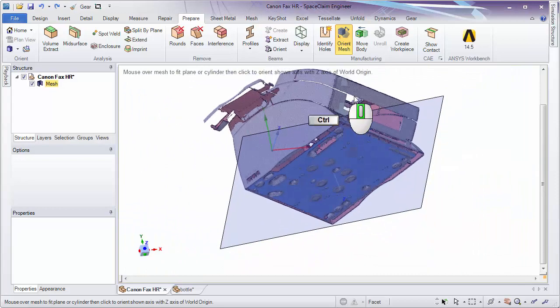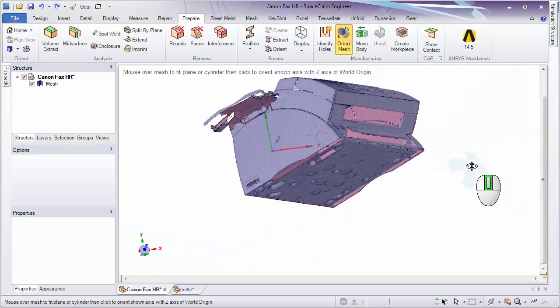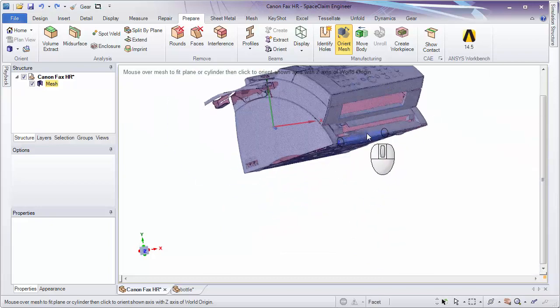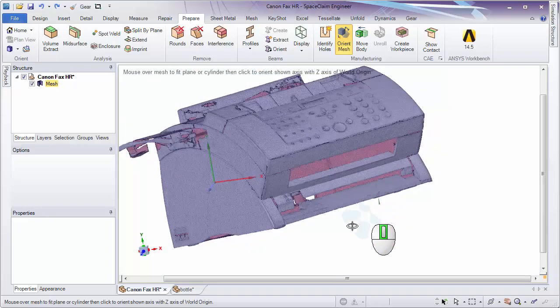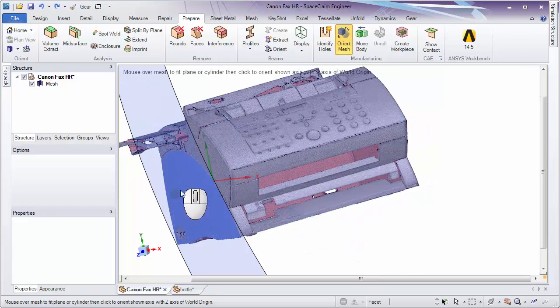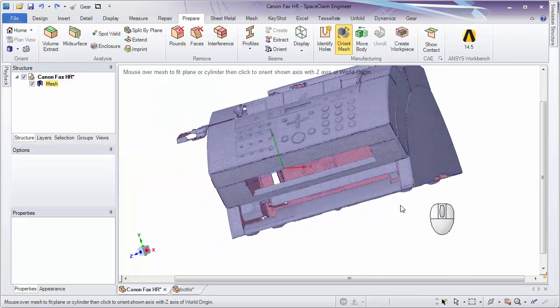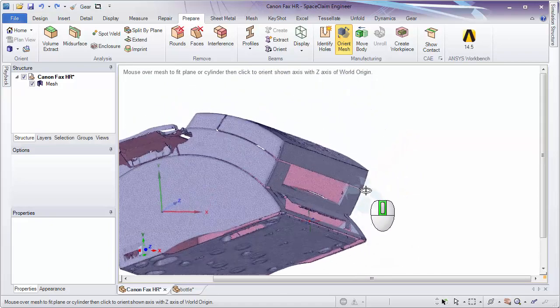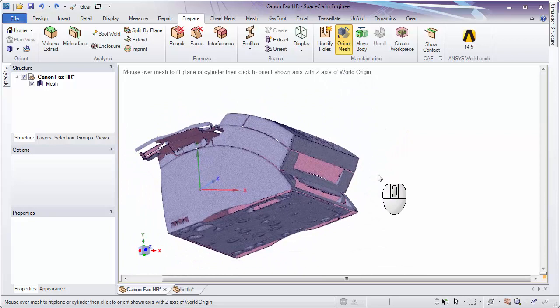I'm just going to hold down Control Z for a minute because we're not always fortunate to have nice planar faces or cylindrical faces to deal with. Also, we may want to center it between two faces which may be drafted. If we just use one face and it's drafted a few degrees, the thing will be skewed a little bit. So we're going to explore a few different methods to put in planes and references.